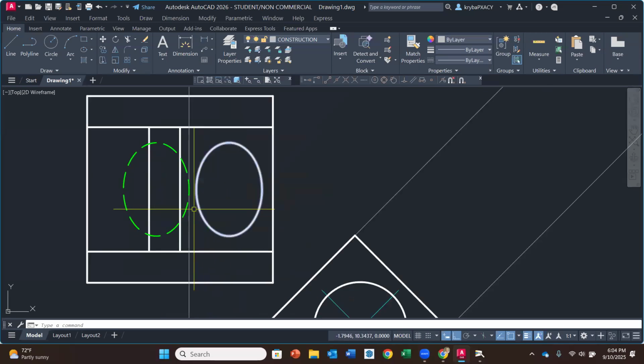Now, the next thing we're going to do is put our horizontal lines to go back so that it exits out the part. So I'm going to go back on my hidden line layer, line at the quadrant of my visible one, and I'm going to go all the way to the end, perpendicular to the left side. Then I'm going to do that same thing at the bottom quadrant, all the way to the left.